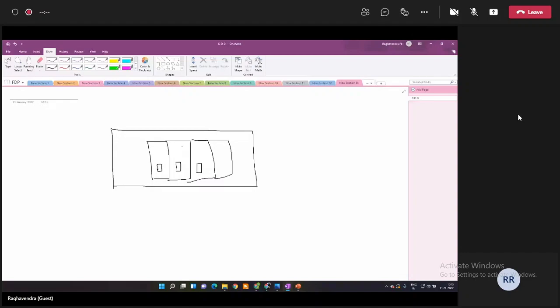And it's not just one type. So if I put, say, a temperature data collection card, which is basically an analog input card, it doesn't mean that I always have to put analog input out here. I can actually put a digital input also. I can put a digital output also, so on and so forth. This has a single interface that connects with whatever system that you're working on.